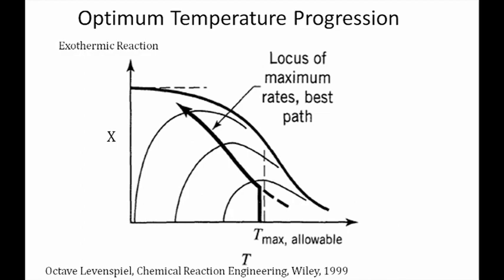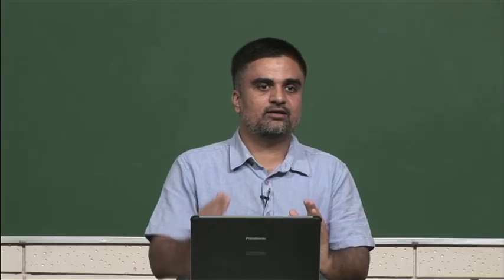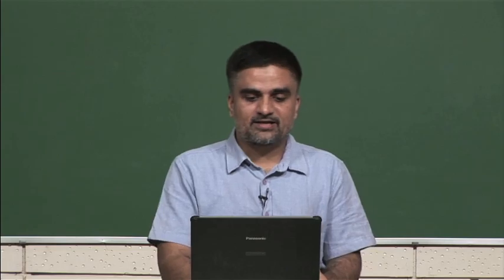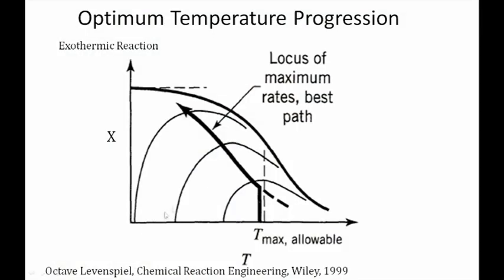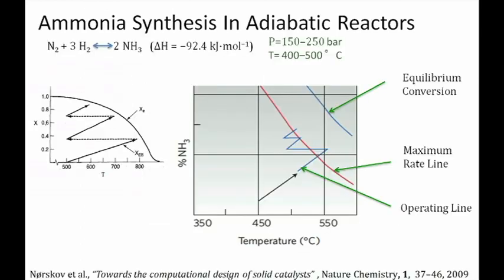Now, this is all coming from the material balance. So, you want to run the reactor here, but the adiabatic condition is saying that there will be a line with a positive slope, and the reactor also needs to follow the energy balance. So, all these conditions should meet together to give you the best performance in these operations. So, how are you going to get it? We will plot it here.